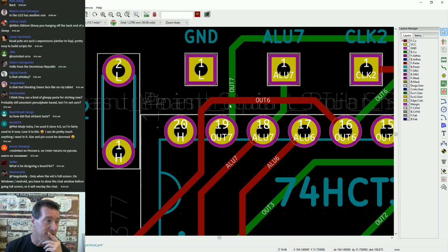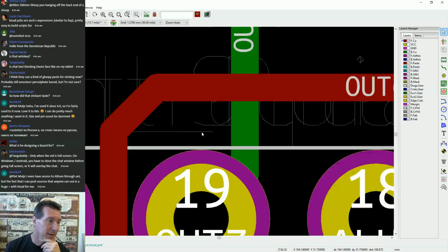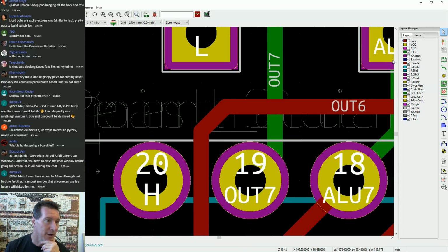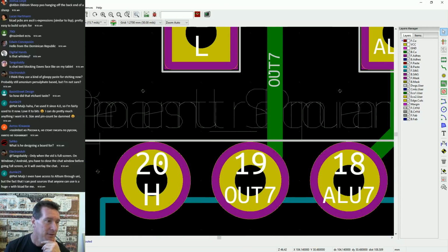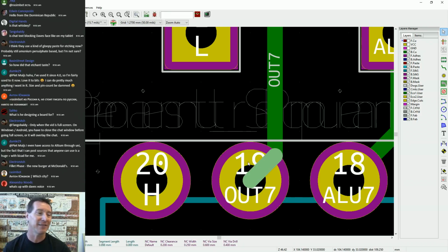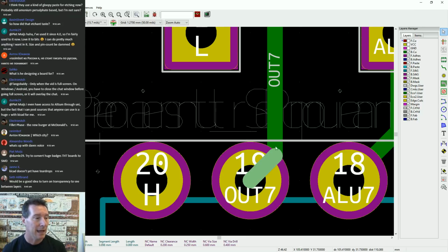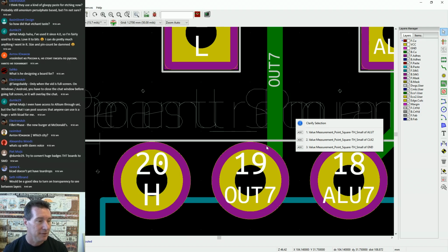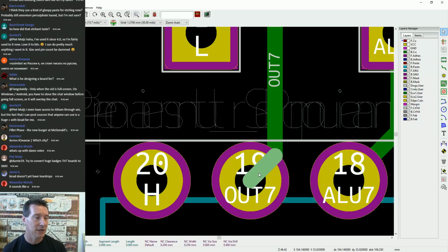Now that we're talking about this, see the problem here is this trace coming down. This is not good layout. You don't have your trace coming down and then at an angle, even though it might be angling in here properly and it might be physically connected. I don't like that. KiCAD doesn't actually... No, there it is. It's hidden. I didn't like that it was hidden. So it's going to the center, which is all great, but then you've created the acid trap in there. It's just not good design technique to do that.